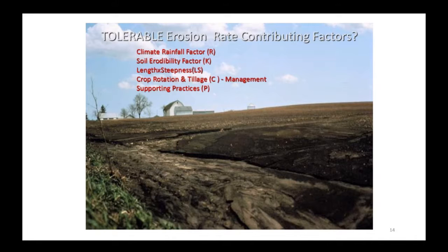Now, that climatic factor that is embedded in RUSLE2 looks at a distribution curve for Wisconsin, or even our region, of rainfall events over a 24-hour period, with the majority falling within 12 hours of that rainstorm. So at the 12th hour of a 24-hour rain event, most of the water would have fallen on the landscape.